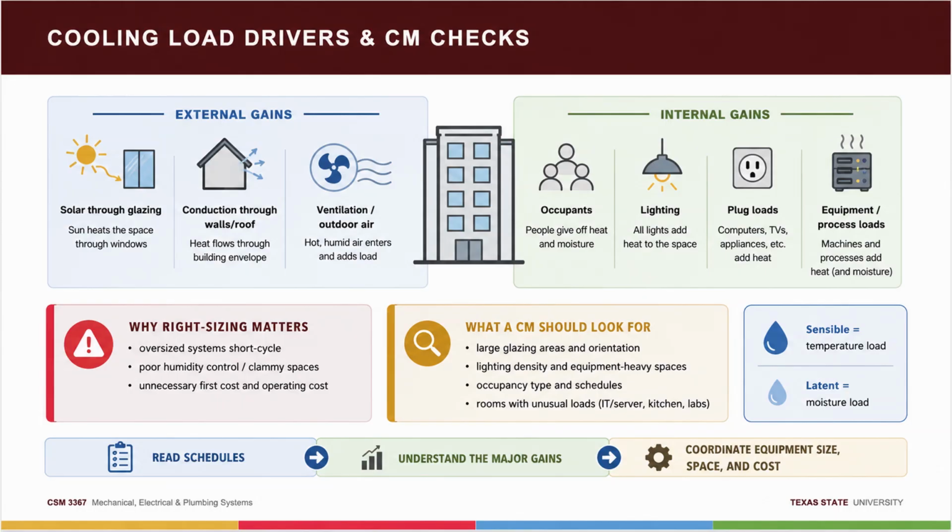Here's the physical picture that makes latent heat click. Go look at the condensate line on any rooftop unit or the drain pan under any air handler in August. Water pouring out of it, gallons and gallons a day. Where did that water come from? Out of the air. And every drop represents energy the machine had to spend condensing vapor to liquid, capacity that did not go toward lowering the temperature. That drain line is the latent load, made visible.